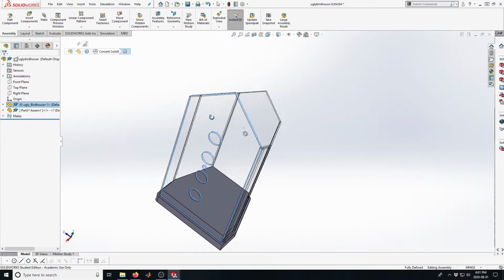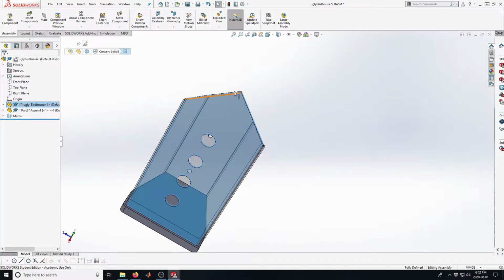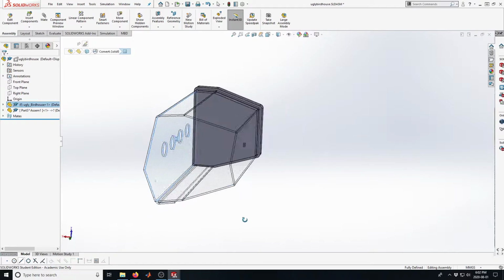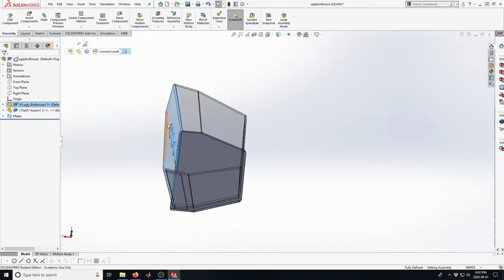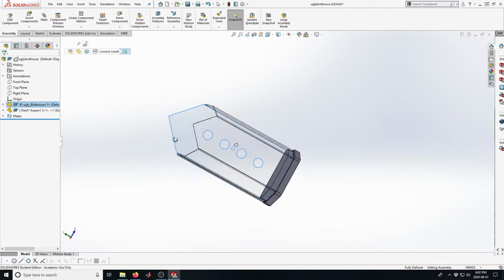The nice thing is there's all kinds of ways to do it. We could look on this view and we could extrude through here along that kind of peak. We could look at this view and we could make a flat plane like this. Both of those would work. The question is, which one's easier? And that's really what it comes down to with CAD, is what's the easiest way to make the thing that you want and make it accurate and realistic?